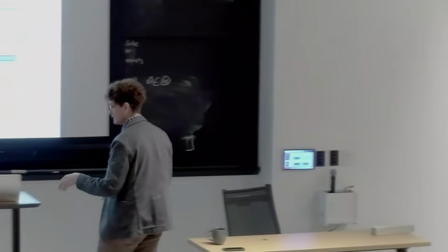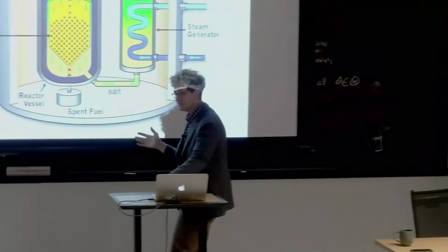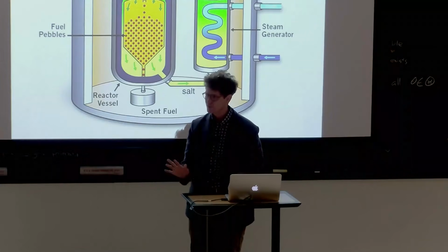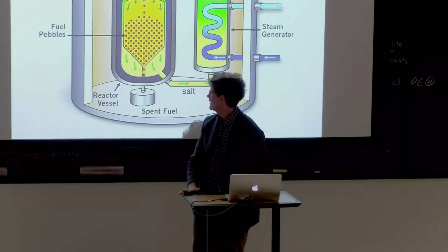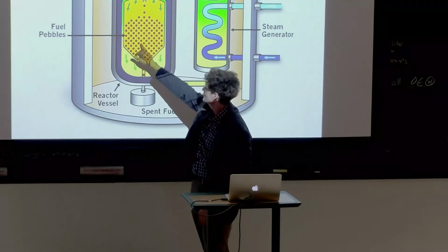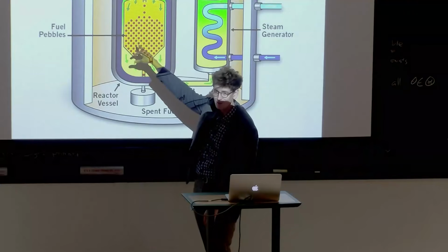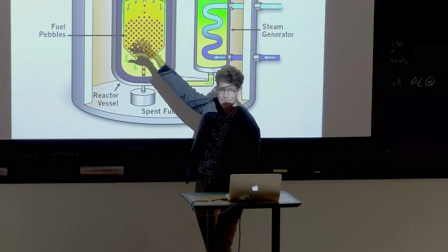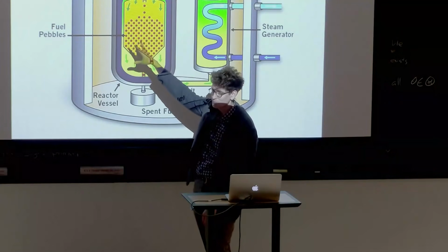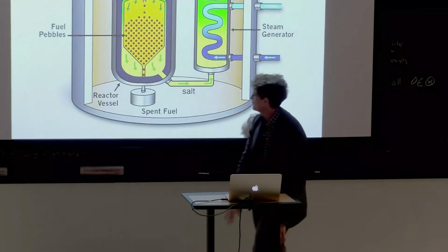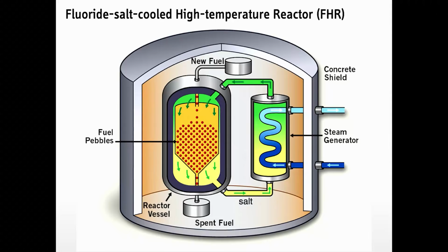One of the problems with helium is that the thermal conductivity of helium goes down when it gets hotter. It's weird. So the result is that on a helium version, if I get a hot spot here, the helium cools it even less and the hot spot becomes even hotter. And then you have the fuel exceeding its design temperatures and problems. So FLiBe doesn't have that feature. And so it also expands less, and you see it's in principle a variant on this that is more robust.